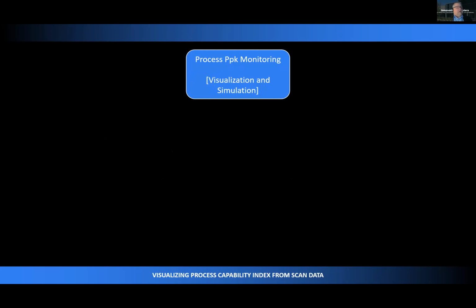A lot of times statistical process control has been thought of as, well, I've got to have 10,000 parts to justify that, or I've got to be in high volume production. And that's not the case. Low volume production is where you need it, especially during prototyping and rapid prototyping, to understand if your process is capable and what your process tolerances are.